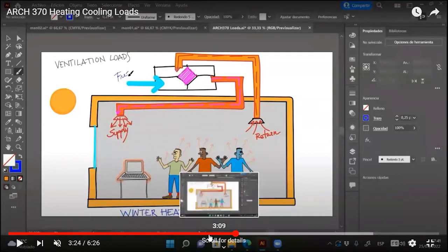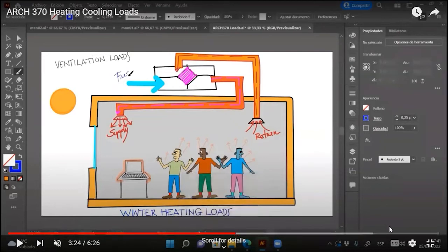How much of the air that's returned is used, and how much fresh air is inside? The fresh air is 20 CFM times the number of people. And the return air is the same. Is it reused as well? It's not reused. We take this return air, 20 CFM per person, to the heat recovery. And in the heat recovery, we reuse the heat. We don't reuse the air. The air that we remove, we don't breathe it again.